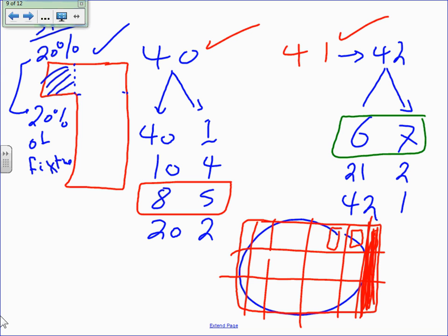If I have 40 fixtures and I will put them in a place, I can either put 4 columns in 1 row, or 10 columns and 4 rows, or 8 columns and 5 rows. The best design, Nick, is to get the closest, the number of the columns and the number of rows have to be as close to each other as possible. For example, I can go 20 and 2, they're way far away from each other. The closest rows and columns are the 8 by 5. If you put 10 by 4, is it wrong? No, but there's a better way of doing it though. Can I get you guys to understand the columns and the rows? So from the number of fixtures, you can decide the columns and rows.